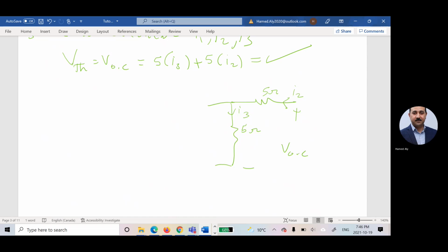Now, I'm going to imagine that this is a closed loop. So this is the direction of the current, so I'll have positive, negative. This is the direction of the current, I'll have positive, negative. The summation of the voltage for this loop is equal to 0. Imagine I'm rotating in that direction. The second sign is positive, the second sign is positive, the second sign here is negative for this voltage. So I'll have positive, positive, negative, which means this one equals the summation of those voltage drops. Got it now? Any other question?